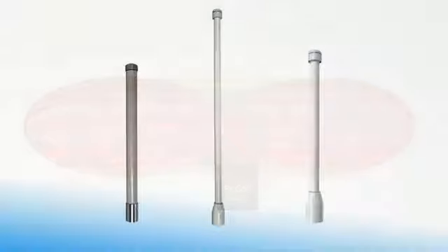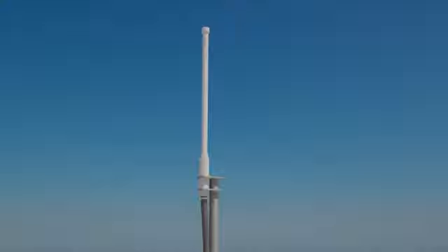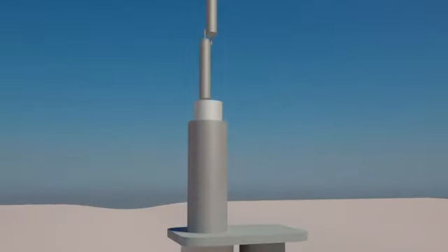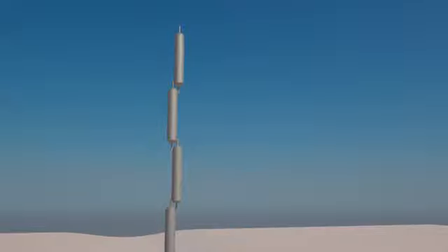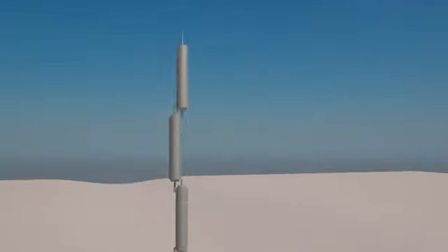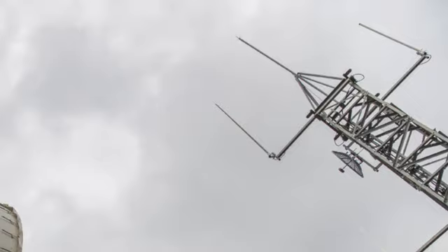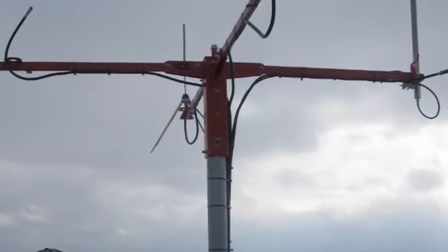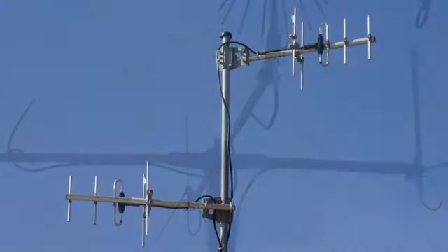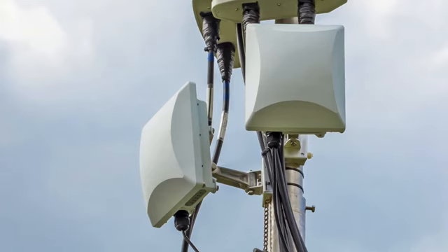Another popular omni antenna is the collinear array antenna. This is typically composed of several linear antennas, like the whip, stacked on top of each other. The more stacked elements within the collinear array, the longer the antenna and the more gain it has. When mounted, the antenna is oriented straight up and down, with the feed line at the bottom. This type is among the most powerful omnidirectional antennas, and so is well suited to situations where the location must send and receive signals from multiple directions. The most common directional antennas include Yagi, parabolic reflector, and panel antennas.